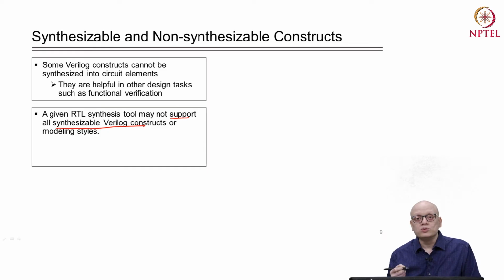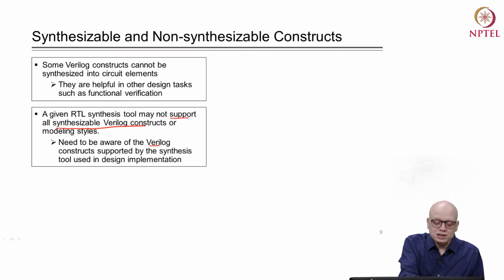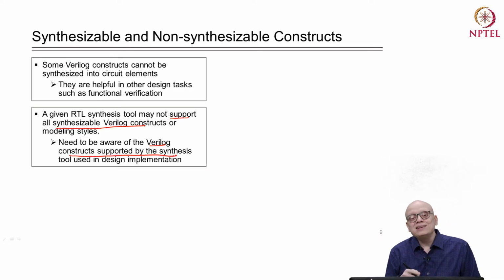This is also a point that should be noted: the language as such does not say what is synthesizable and what is not synthesizable. It is very much tool specific which RTL constructs are supported by the tool for synthesis, and which constructs are not supported by the tool. Therefore, as a designer, we should be aware of the Verilog constructs supported by the synthesis tool that we are using, and write our Verilog code taking that into account.